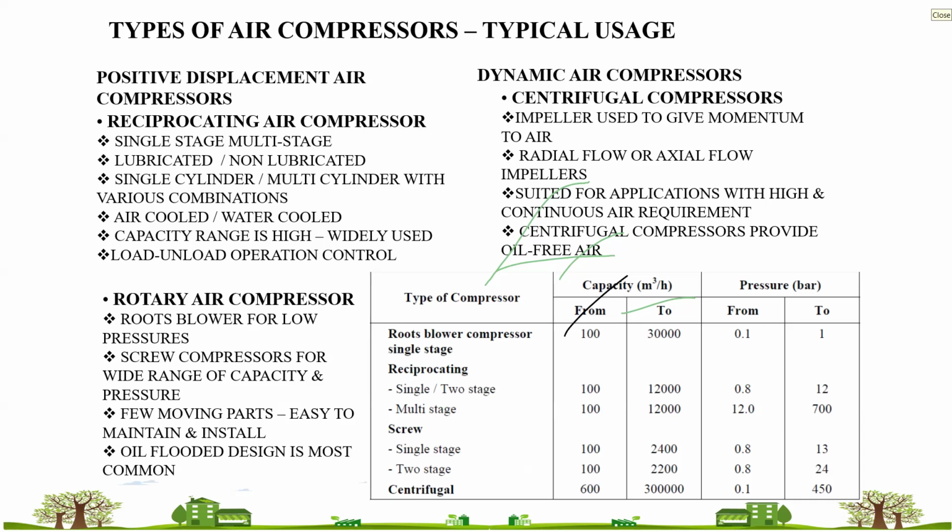Suppose we are going for LEED or IGBC certifications for green building. In that case, what are the standards for these air compressors? Need to check that. But majorly your air compressors are selected based upon your specific power consumption or specific energy consumption, like kW per CFM. That is the major selection criterion.